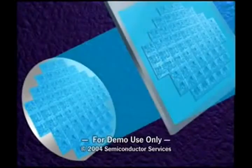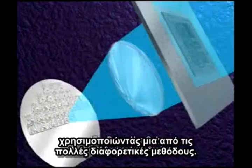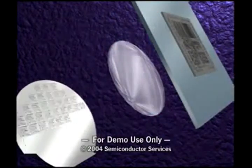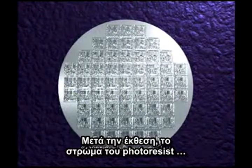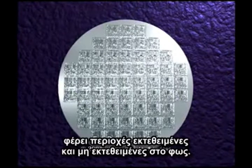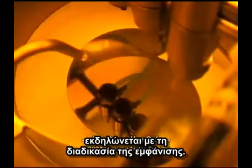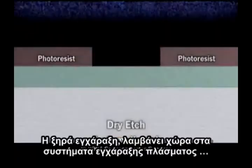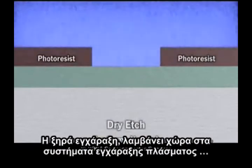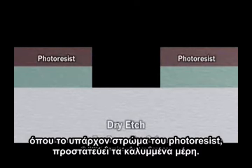to the wafer and then transferred into the photoresist layer using one of several different approaches. After alignment and exposure, the photoresist layer has regions of exposed and unexposed resist. Bringing out the pattern in the resist layer occurs during the development process. Dry etch takes place in plasma etch systems, where the patterned photoresist acts as an etch stencil.